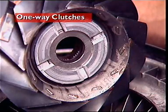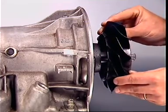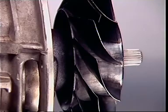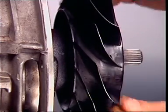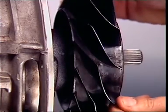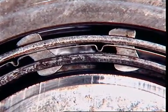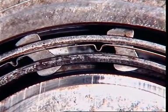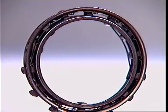In the Sprague-type one-way clutch, the inner race has a central spline. It locates on the stator support shaft to hold the race stationary. The outer race is part of the stator hub. It turns with the stator in the direction of engine rotation. Equally spaced sprags between the two races produce a wedging action to stop the stator rotating in reverse. The sprags are held in place by a spring-loaded cage.